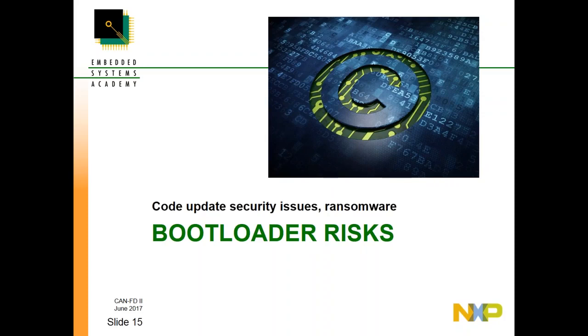machinery. However, what happens today is that more and more CANopen networks suddenly get some remote access. There are so many CAN devices with Bluetooth, CAN to Bluetooth, CAN to hotspot, wireless, Wi-Fi, and these things. So even a network that was never intended to have remote access might suddenly end up with some service technician or somebody who buys a sniffer dongle saying, oh, let's plug this in and see what happens. And suddenly you have access with the smartphone to your CAN network. And so really, the risks we have to now review.